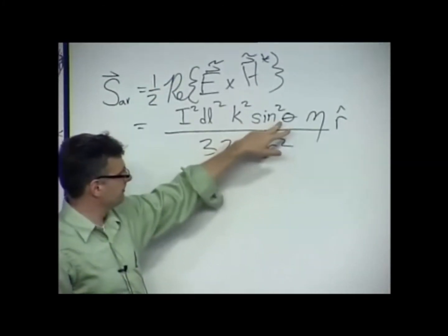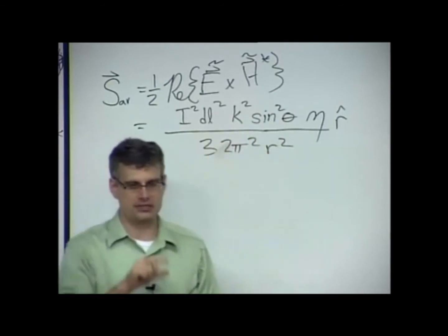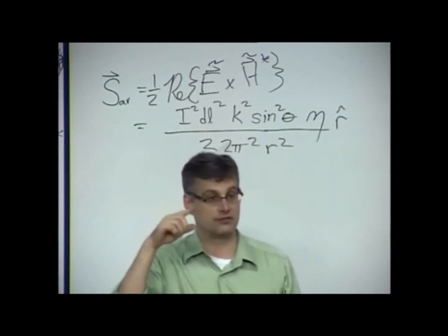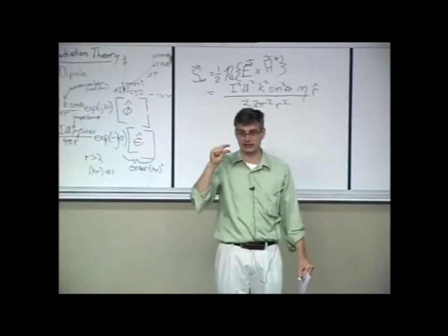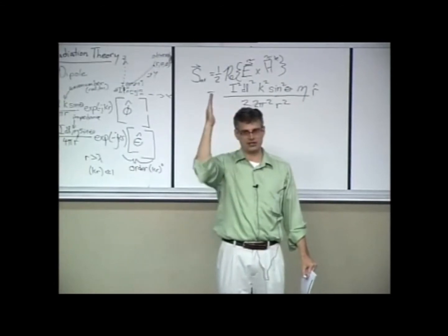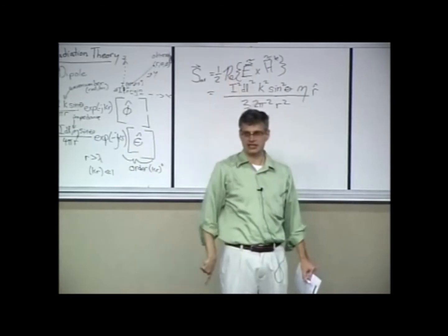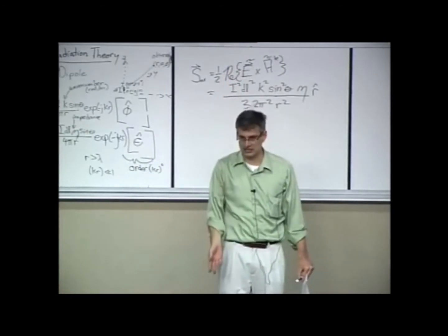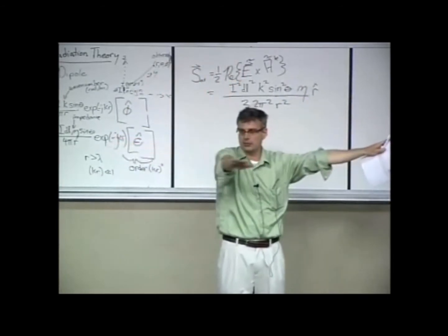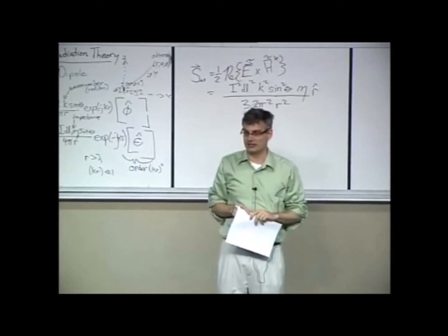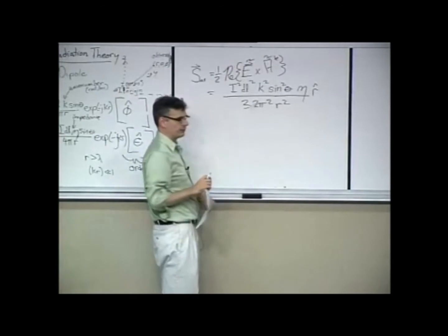And then over here, the only angular dependence is this sine squared theta term. It means my little Hertzian dipole radiates, first of all, there's no dependence on phi. That makes sense. It's a radially symmetric problem no matter how I look at it. It does have a dependence on elevation. There's a null at theta equals 0, which would be right along the z-axis, and also theta equals 180 degrees, which is negative z-axis. It's at a maximum down at the horizon along the xy plane, the way that I've oriented this problem. So that's how the power flows.